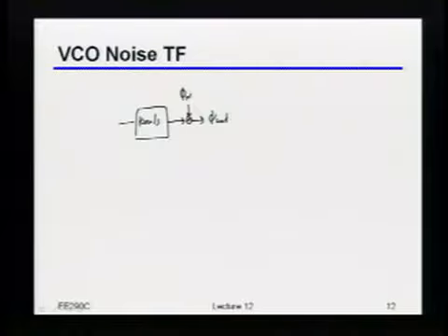So it turns out that typically the way you model noise on the VCO is not necessarily to just directly add it. Let's say this was your VCO model, just KVCO over S, an open loop VCO, and I wanted to add phase noise at the output due to thermal noise inside of the VCO. It's a little bit problematic, because technically this would go to infinity. It would have this infinite spectrum. Okay, so that's kind of a pain to deal with.